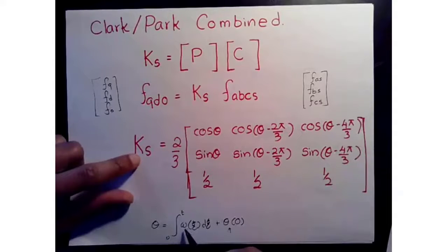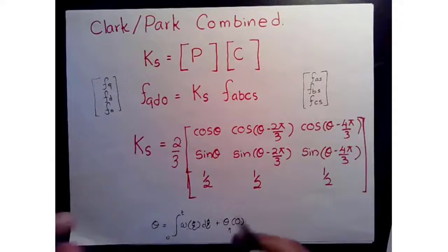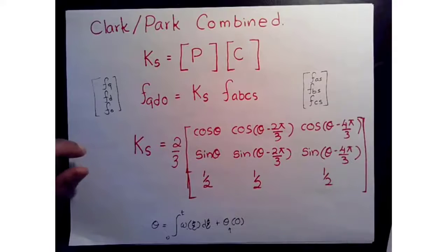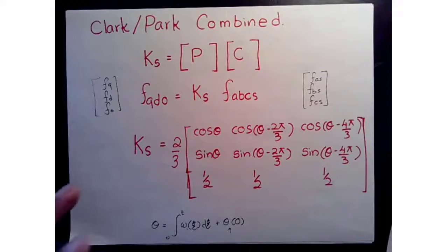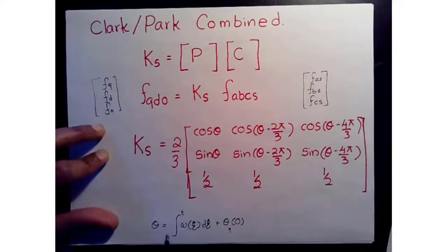You can choose this frequency to be any frequency. It need not be your rotor frequency or your stator frequency. It can be arbitrary, because that way we study the math in a more generic sense. But now when we go into our machine analysis, we can apply it to the specific machine using the frequency of interest. For synchronous machines, typically we use the synchronous frequency to study the machine. Okay, but you can look at it from any frequency.